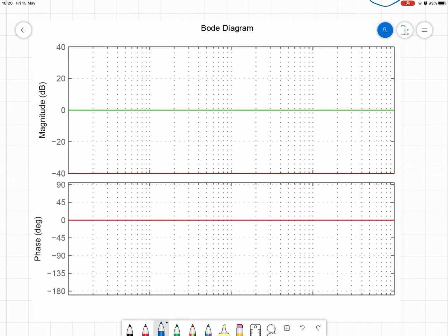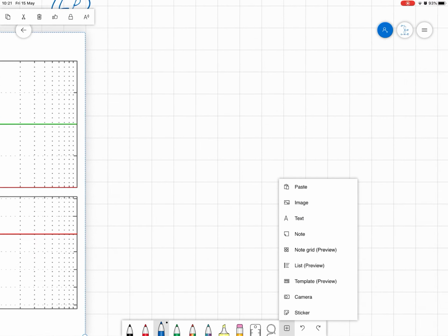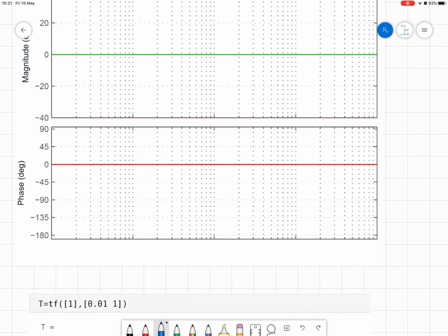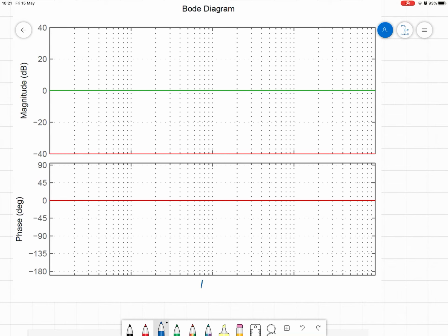We put the critical frequency at the center of this Bode diagram. So we say 100 is the frequency that we put at the center of the diagram. Then the next stop is 1000 because we're in a logarithmic scale, and the one to the left is 10, and these are radians per second. Now we can put our critical frequency in here. -3 decibels is approximately here, so we know we have to go through this point.